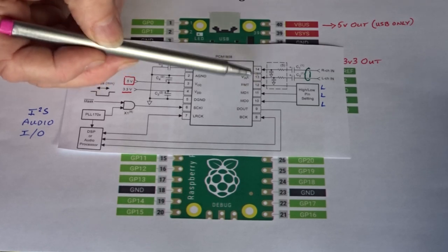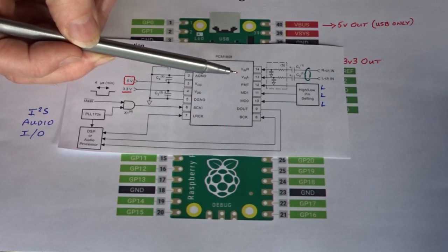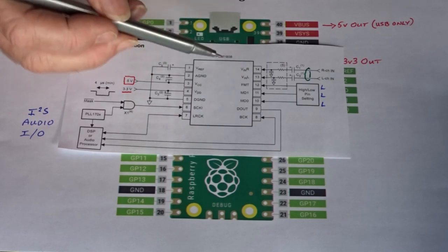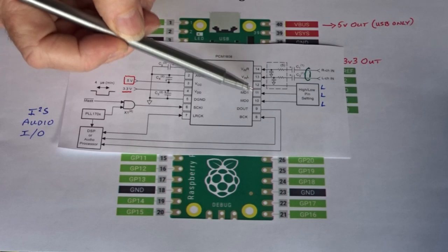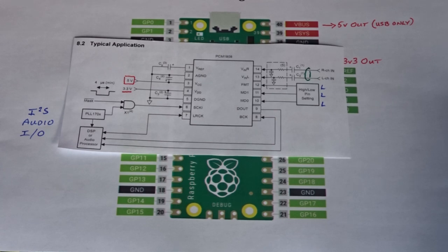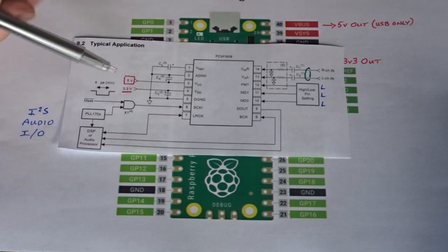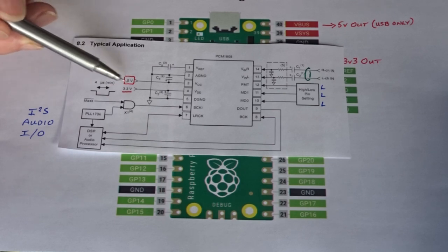So here again there are some control signals. Format, you set low for I2S, and the mode, it can either be a principal or a helper device, so it's either the one that's in control, the controller, or it's the one that's being controlled, and by setting them both low, this is the one that's being controlled, so it's taking its serial clock from elsewhere. It's not expecting to drive it. And I'll probably just connect the left and right inputs together so that they all take the same signal, and we've got a 3.3 volt in, ground obviously, and a 5 volt.